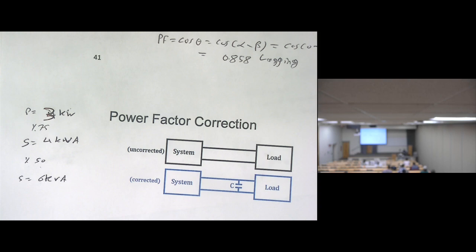If your power factor goes below a certain value, and you didn't take any action for a certain period of time, then there will be a penalty. That penalty makes you pay more money to the utility, because it's like they're giving you a ticket because you didn't improve your power factor, since this is affecting our system.